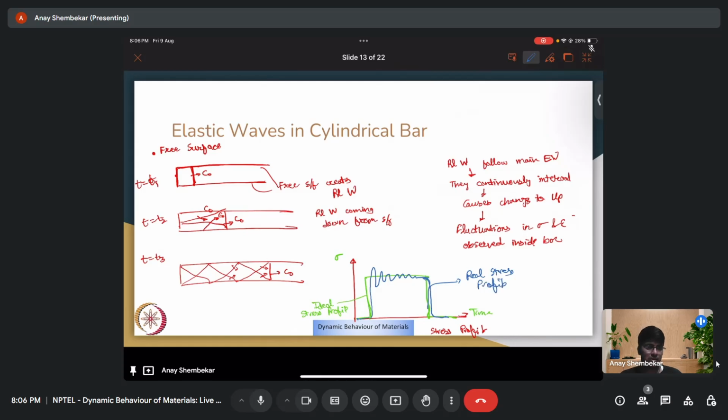When we perform a split Hopkinson bar experiment, we do not get an exact rectangular stress pulse. We get something with oscillations. And we already discussed that these are accounted for by understanding the role that the free surface plays in this experiment. And the radial inertial factor would cause effects on, say, the time of arrival or any delay that we see.